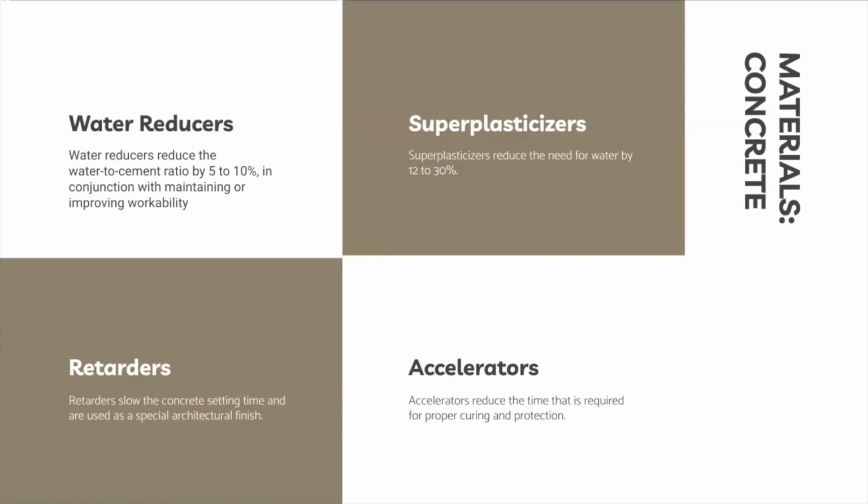When using multiple admixtures, it's essential to ensure compatibility with each other and with the cement, consulting the manufacturer for guidance and possibly conducting trial batches.